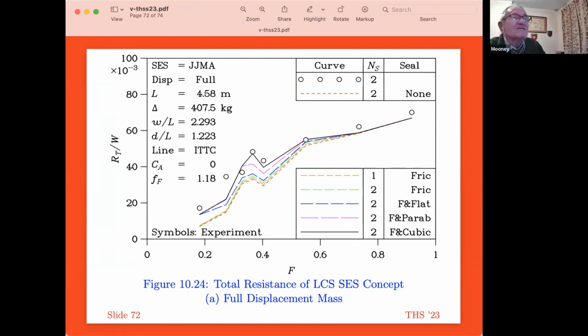You were talking about puff ports and skirt lip, where you had hydraulic rams operating the skirt lip, and later puff ports were introduced. When we were operating SRN5s and SRN6s, we had both. The hydraulic rams lifting the skirt, one at each corner. So if we pulled the control to the right, it would drop the skirt on the left, and the craft would lean to the left for attitude.